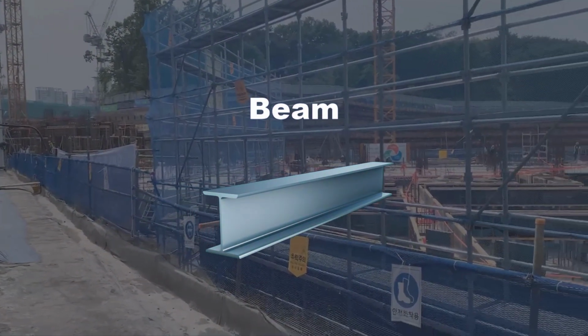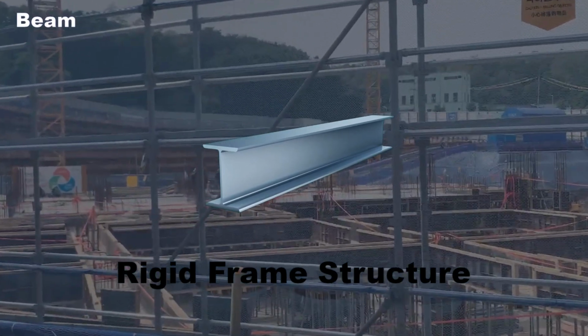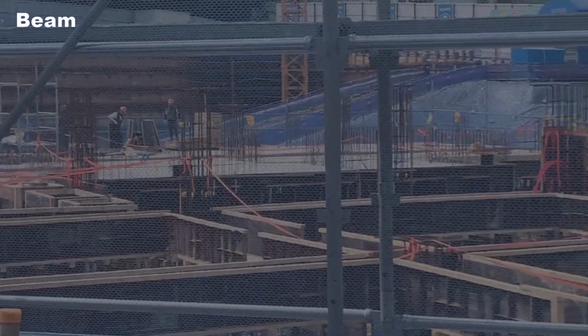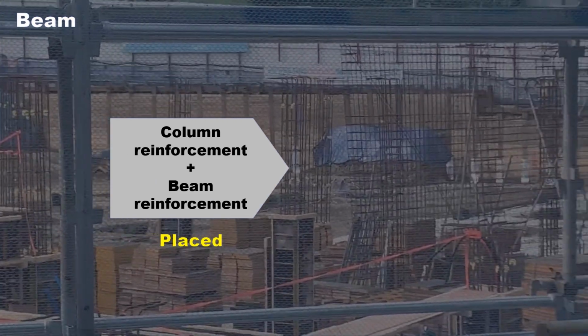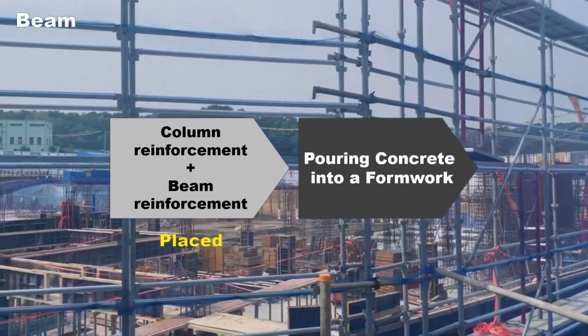Secondly, beams. The important point of rigid frame structure construction is that we have to install the beams. After the installation of the columns is completed, the beam reinforcement is connected to the column reinforcement and placed in the formwork, and then concrete is poured into the formwork.